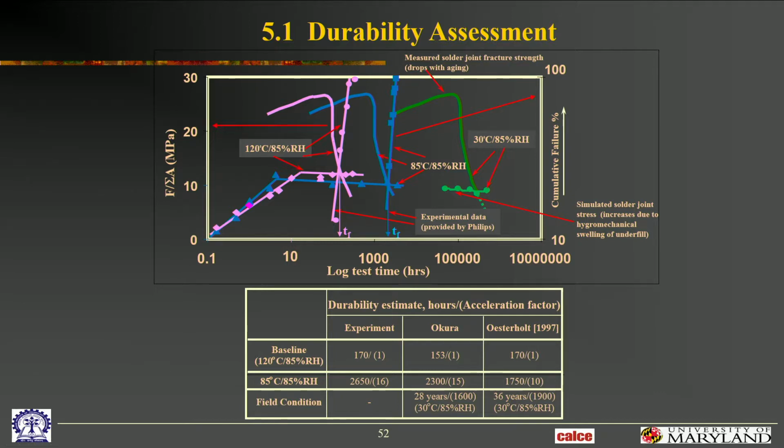And the sponsor was not at all happy with that. Why? If you apply the same acceleration factor to the early failures, you find that it's barely 2 to 3 years. And that's definitely not enough for the sponsor's requirement. The reason they were failing so early is that these Weibull slopes are too low. That means that variability is way too high.